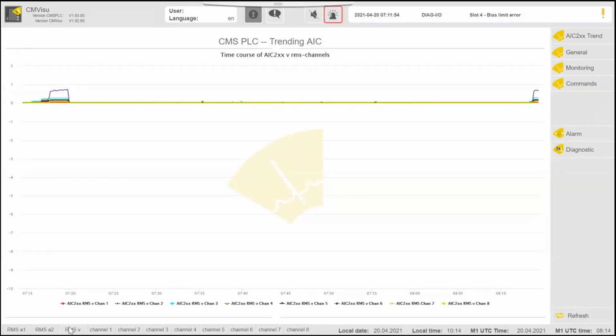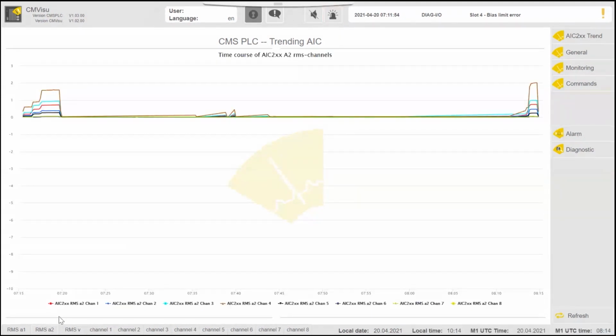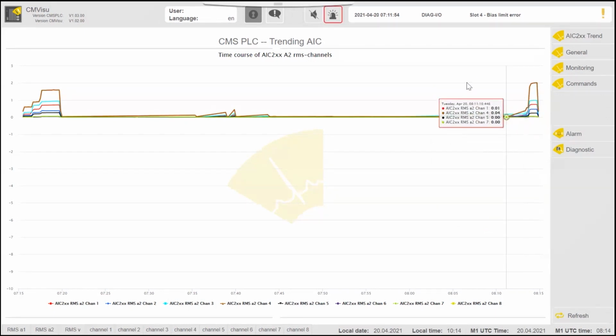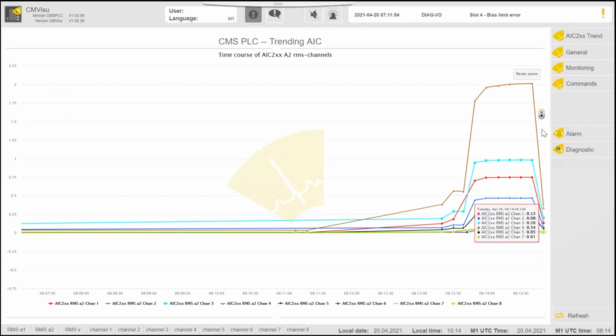I'm afraid the noise is rather high, so I've switched the machine off now, as you'll have realized, and then the levels will show up again as coming back down to a lower level. So you see we've come back down again after that period. But what we can also do during this measurement is we can take a more detailed measurement, which creates a waveform from the vibration of the machine, and that measurement can then be sent off either off ship to a specialist on shore, or if you have a specialist on the ship, somebody at the ship can take it away and look at it in a more detailed system.